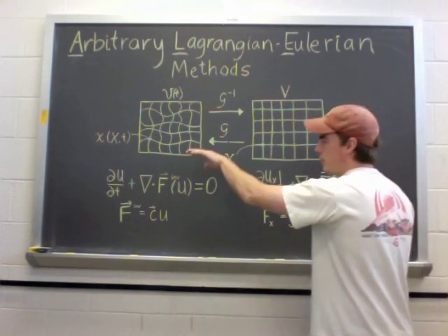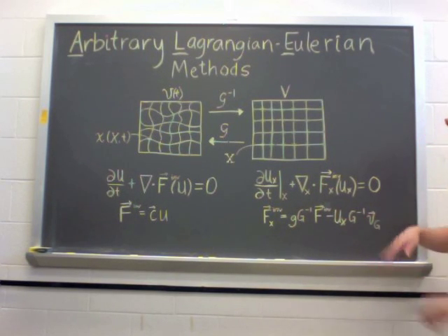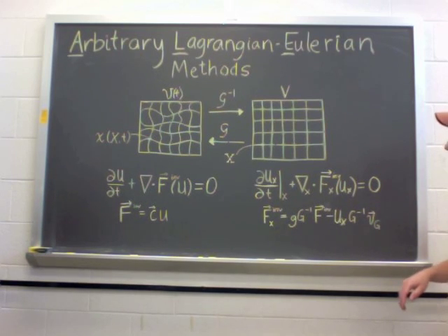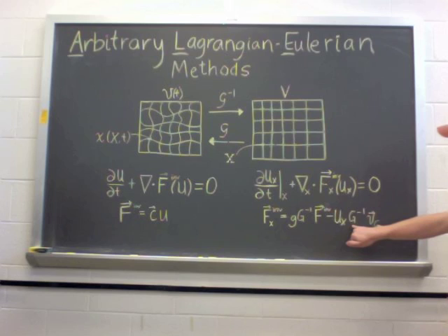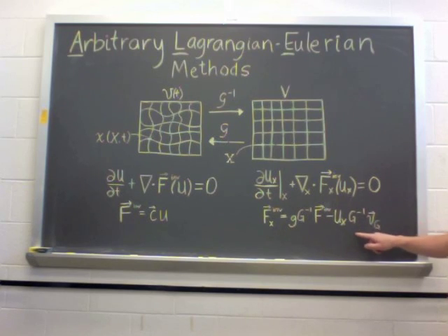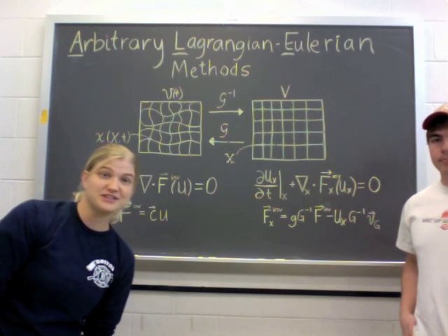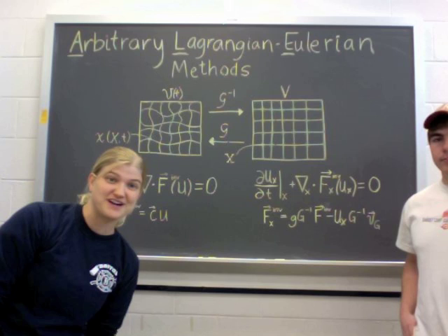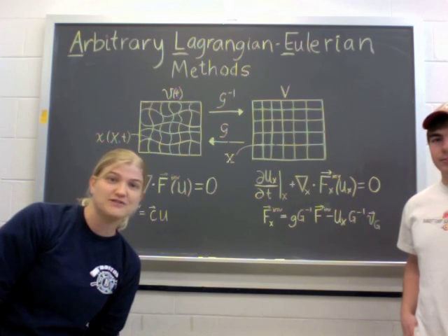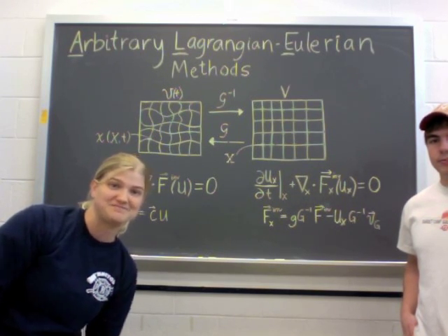But to include the moving geometry, we also have to include this term, which corresponds to fluxes from the moving mesh. So again, we have the inverse Jacobian. This is the mesh velocity. And this is, again, our conserved variable. So this is kind of like a convective flux coming from the moving mesh. In calculation of the flux, you'll quickly find lies the crux. After accounting for mesh deformation and speed, the fluxes are calculated and we proceed.